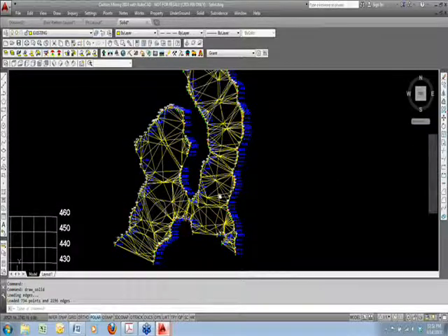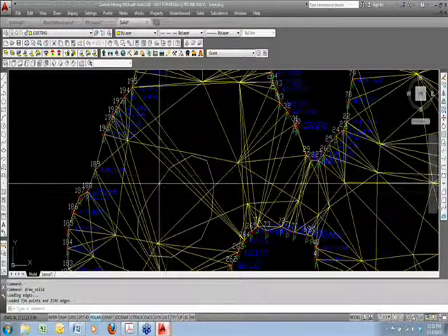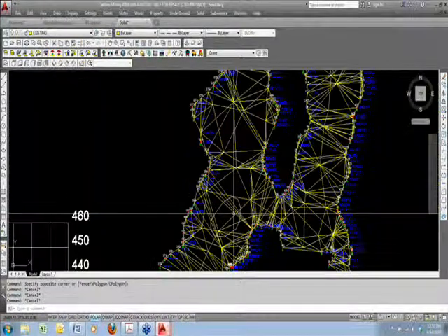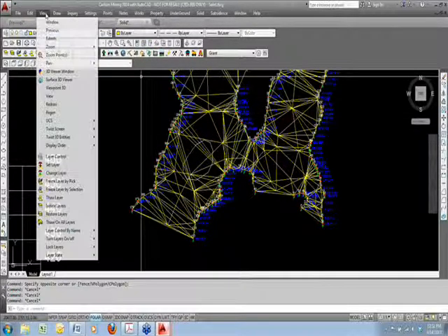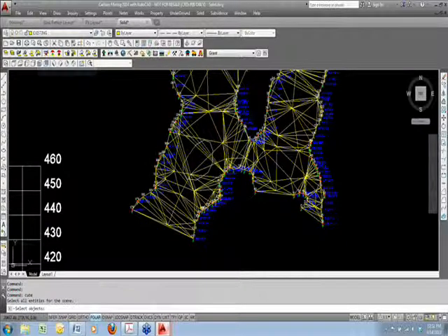It also handles internal polylines. So this is an internal polyline that I've drawn, also 3D, and that would be an exclusion. So that could be a hole in my solid. And so before we view that, well, I guess we'll go ahead and view it first, and then I'll remove it and recreate it with that hole. Go to my 3D viewer window.